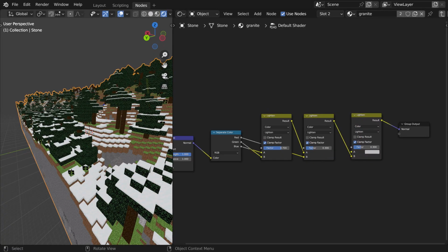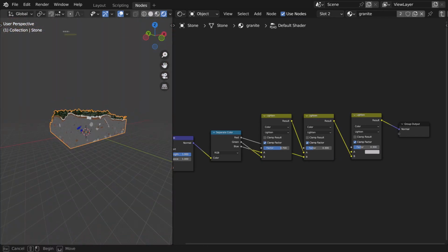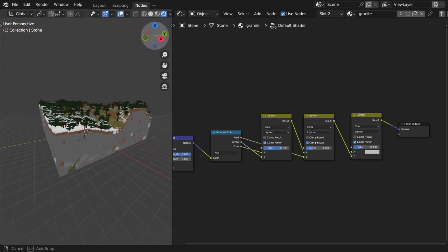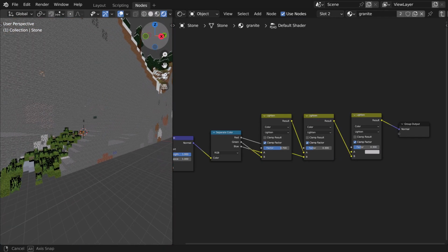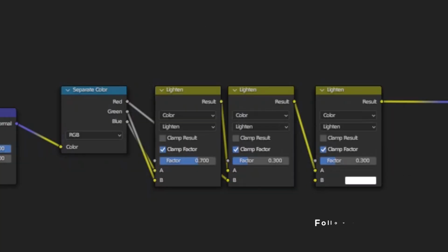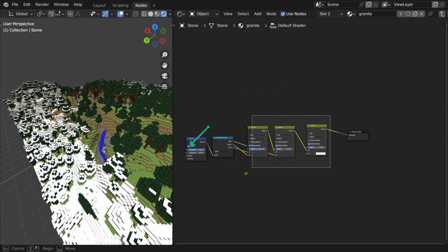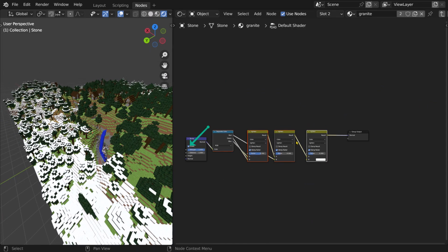Well, the world looks good and nicely lit, but it looks a bit like sunset time because the color we used to eliminate the black is a bit closer to gray. To solve this problem, we have to change the mix color type from lighten to mix only and make the other color completely white. Don't forget to invert the bump effect here.